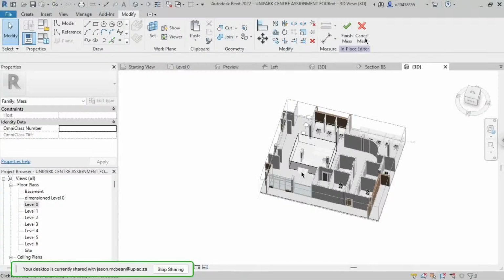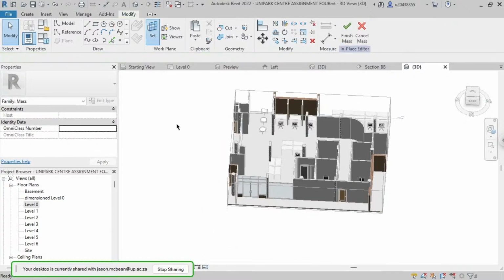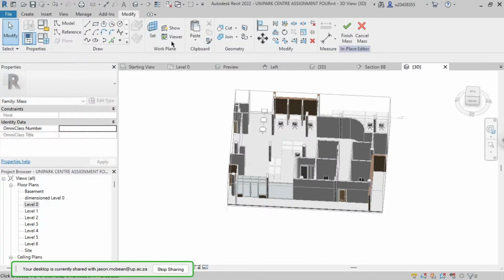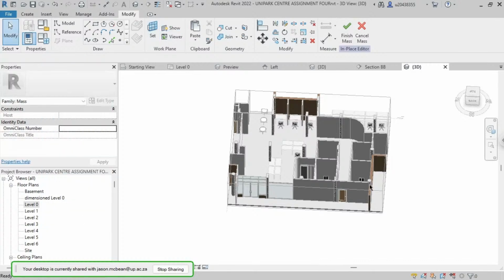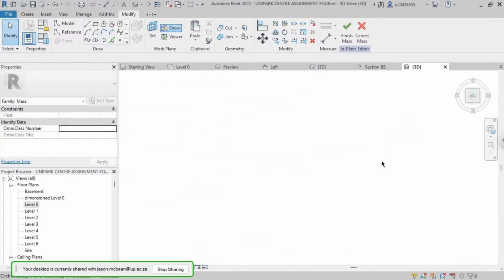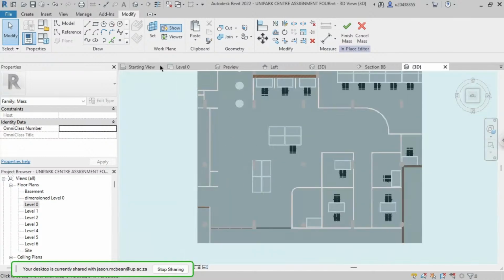Yeah. Okay, good. Now we're in business. All right. Good. Now I can double click, get rid of this, delete it. I don't need it anymore. Okay. Now set your work plane. You'll notice now that my reference plane has that name. Set ceiling. Now you can also say show so that you can see the work plane. That's important. Okay. Now, to create an organic type of shape, we're going to go and use reference lines in this instance.